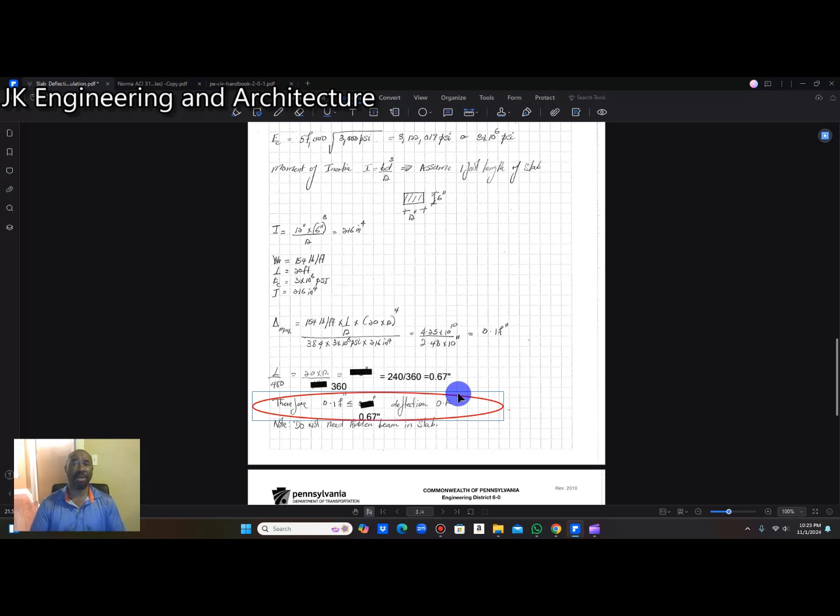And again, from my perspective, a sleeper beam or a flat beam is a stiffener. Okay, it is not a load carrying member per se. When you put in a flat beam at the center at midspan, you're only stiffening the slab at midspan to limit the deflection.